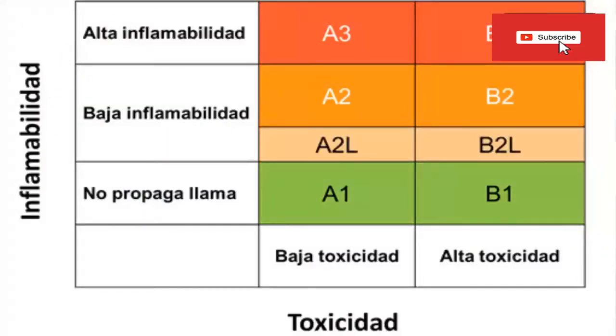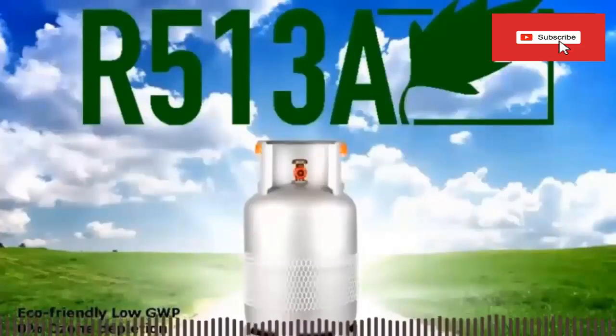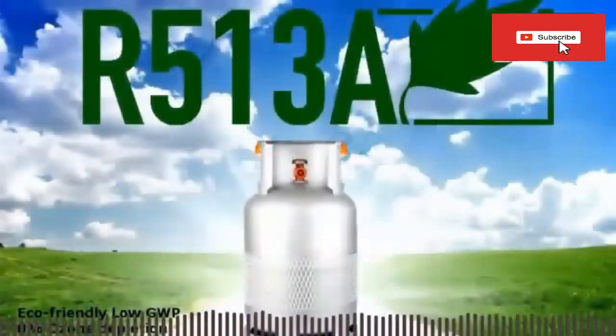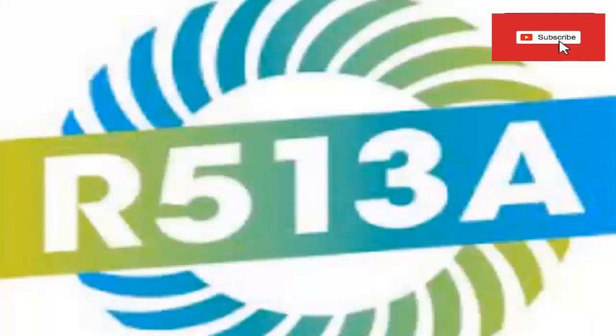3. The R-513a refrigerant has a GWP of 631, but has a weak point with a slightly lower efficiency than R-134a. 4. R-513a refrigerant is a drop-in, direct replacement for R-134a, in existing high and medium temperature commercial and industrial refrigeration equipment, positive displacement and direct expansion.